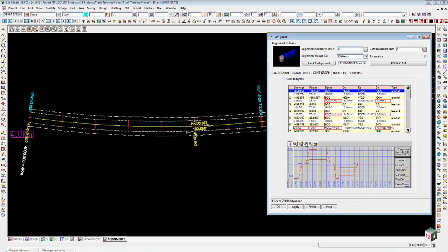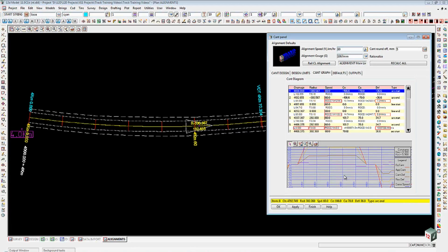I can go and zoom a window, so I'll start with the zoom window, pick on that button there, select the first part of my window, drag out, select the second part of my window, and instantly that updates for me inside that little view.